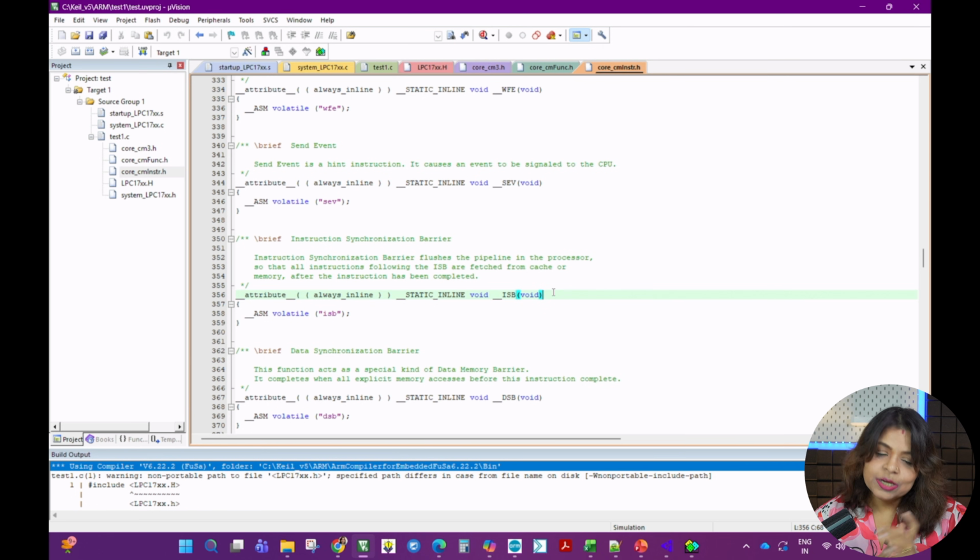Learning assembly is very crucial, even when you are developing the code in C. Sometimes your code doesn't execute, and when you're trying to check why the code is not executing, depending on the IDE software you're using, like if your program is using some library functions and you don't have the definition of those libraries, you can still see that in the form of opcodes, because a library is nothing but a set of object codes. You can see all those in opcodes.